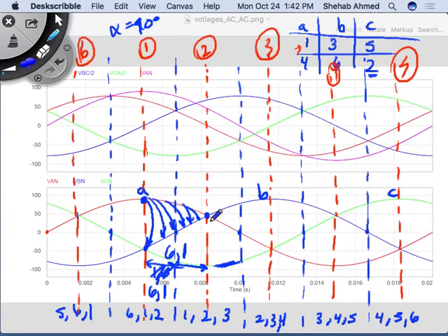So current would easily find the route to return through phase C negative, and I just turned on device 2 here. Here, what's going on? Here I had 1 bringing current from my source, going back through device 6, right? I am no longer able to do that because actually phase B and A swap polarities. The voltage difference between them swaps.